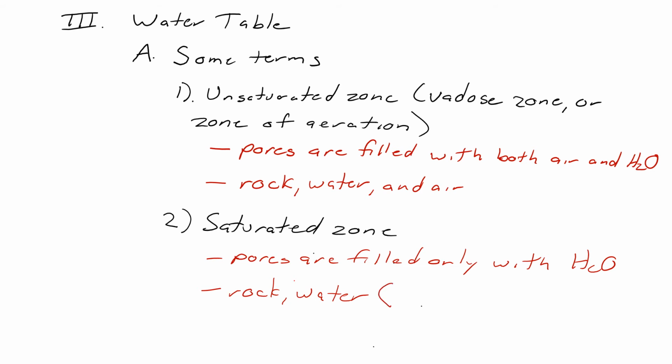So it's that simple. Also remember, and this is something we'll get into a bit later in the semester, water is incompressible. So when it's in the pores, it can't be squished. And remember, when you're in the ground, you're always going to have pressure from gravity pulling down all the overlying rock. So you can have quite a lot of pressure on these systems. But if there's water in the pores, then the water, because it can't be squished, actually acts as support for the rock.